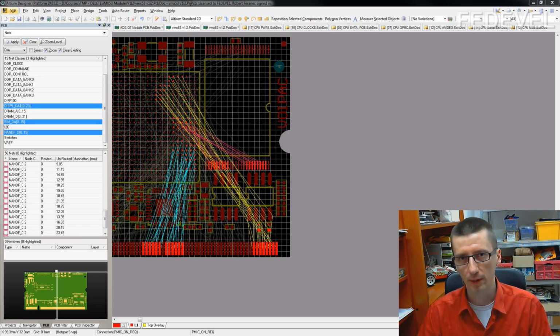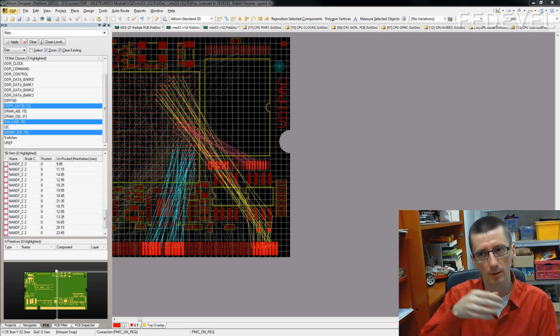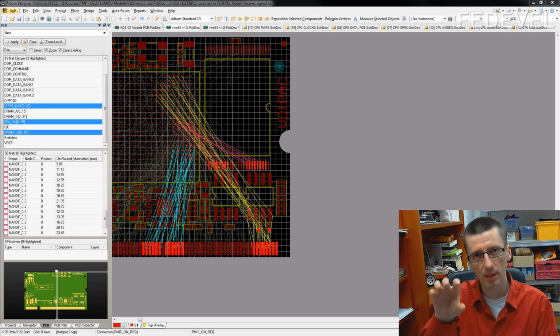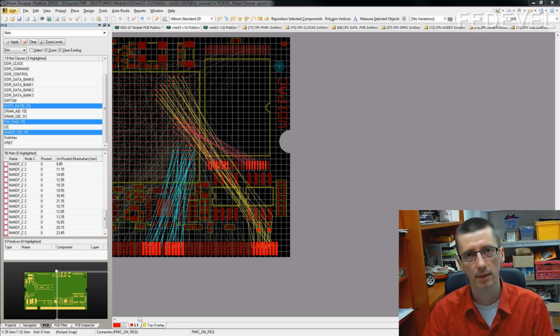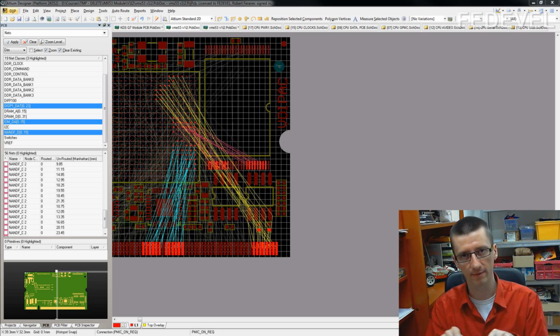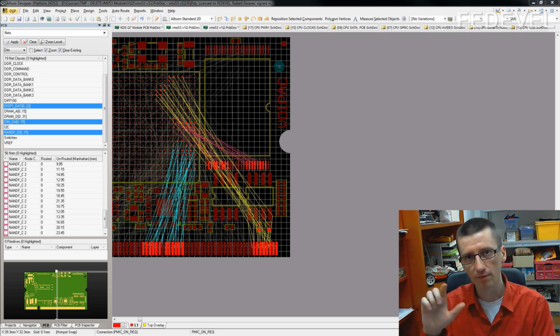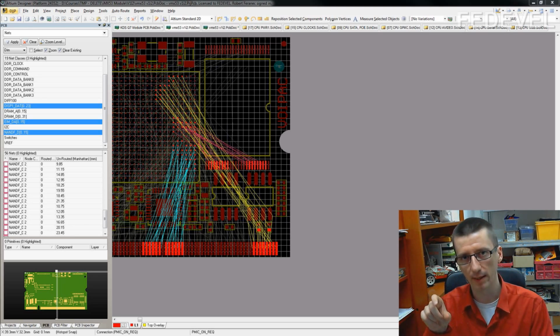What you need to be careful about are the big violations, when you have a lot of tracks and you have a via just in the middle of all these tracks. You need to be sure there is enough space to go around the via, otherwise it may be very difficult to fix later, because making space for 3-4 tracks to go around the via may require moving a lot of the existing design, a lot of the existing layout.